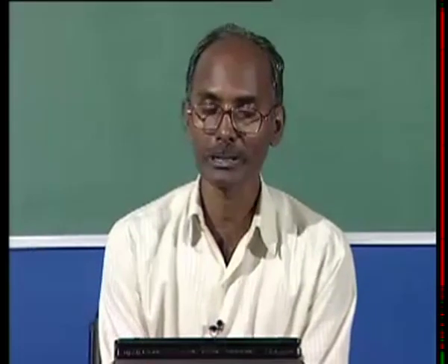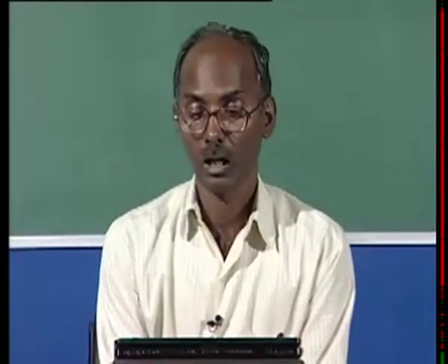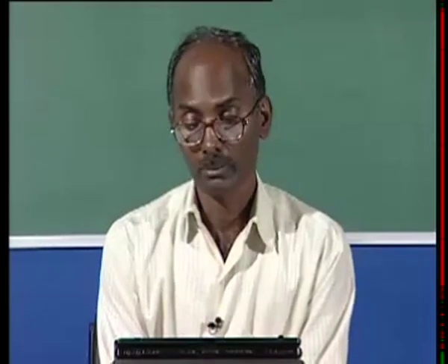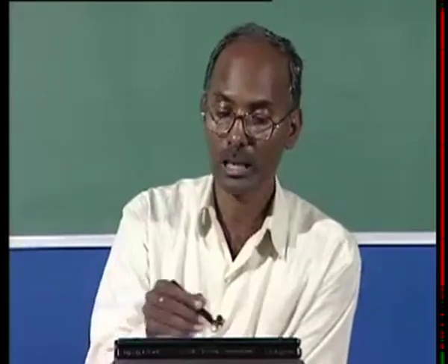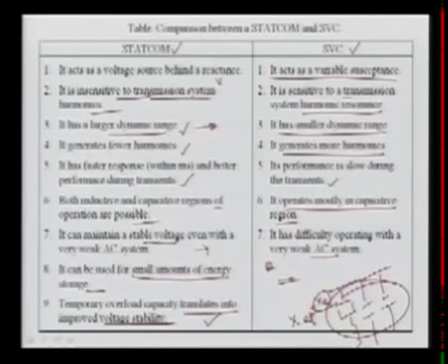But the main problem with the STATCOM is that it is more expensive than SVC, and due to that, SVCs are very, very popular, and they are already located at more than 750 locations all over the world, feeding almost more than 40,000 MVAR power to the system. So SVCs are very popular. I will show you later how they compare and which is better. Again, based on that, we will compare in the next lecture.